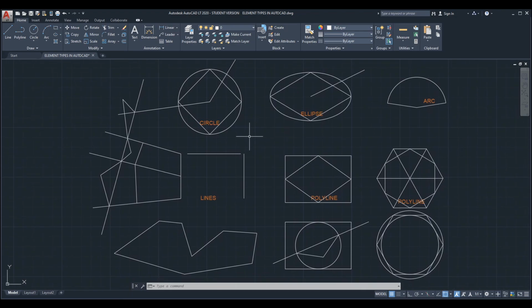All right. And that was it regarding the snap settings, or the basic snap settings in AutoCAD. The endpoint, midpoint, we got the center, we got the geometric center on these two geometries or on this one. And I also showed you intersection, and better have apparent intersection active with it as well.